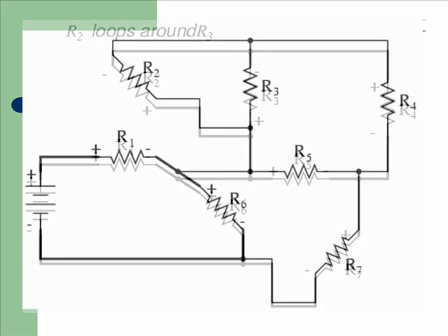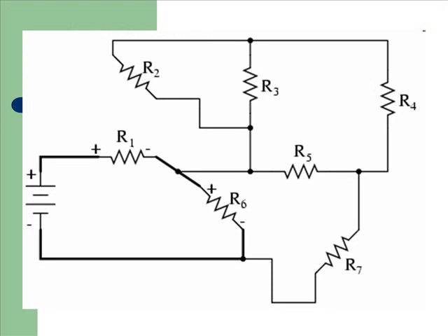With only one remaining resistor left to trace, the next step is obvious. Trace the loop formed by R2 around R3. Adding R2 to the vertical drawing, and we're finished. The result is a diagram that's very easy to understand compared to the original.